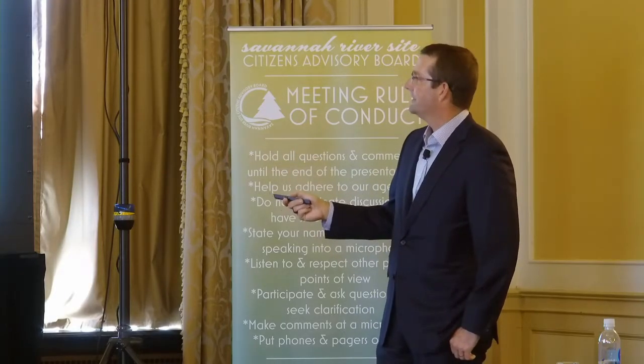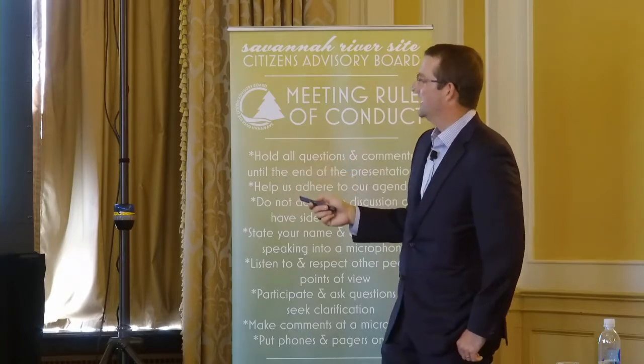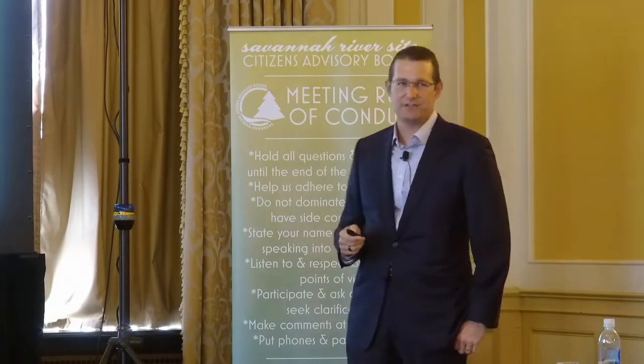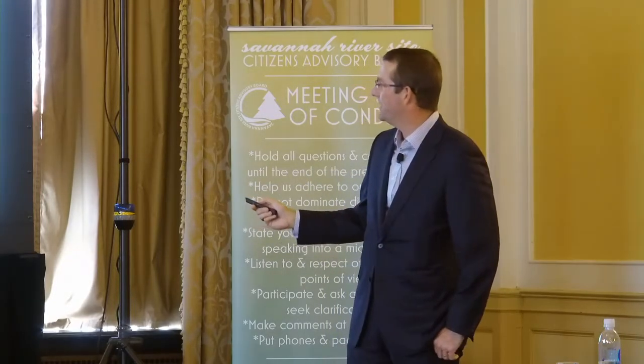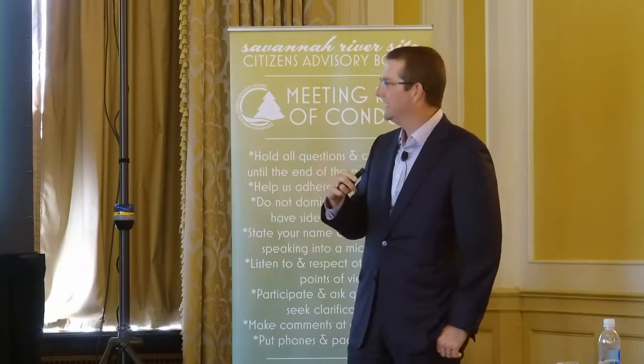Coming out of the hopper, you go to our grout pump. This picture is taken from above again. And this is a peristaltic hose pump, and it's one of the biggest hose pumps I've ever seen. It has 2 pump heads. Each of these pump heads is about 4 feet tall. And each time that pump rotates 1 full revolution, it will discharge 10 gallons of product.